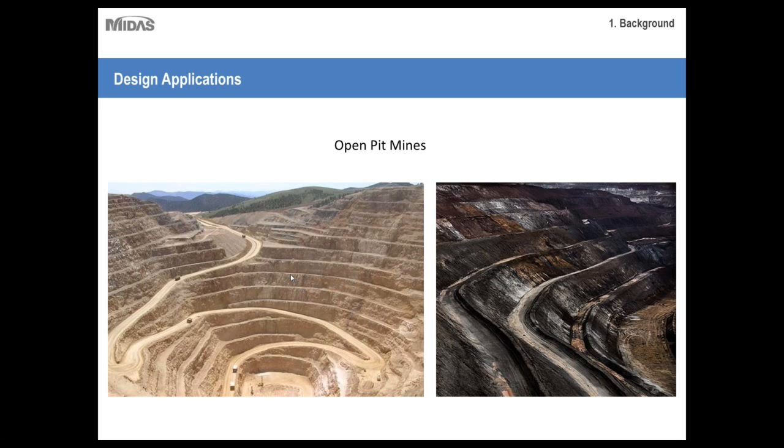But because we wouldn't want any failure to occur, it's always a very good rule of thumb to check for the stability of these various slopes, and also to check for structural weaknesses within the rock, such as faults, shears, joints, or foliations. Those are important things to consider when constructing these open pit mines. But there are some instances where additional ground supports are required, such as rock bolts, cable bolts, and shotcrete.